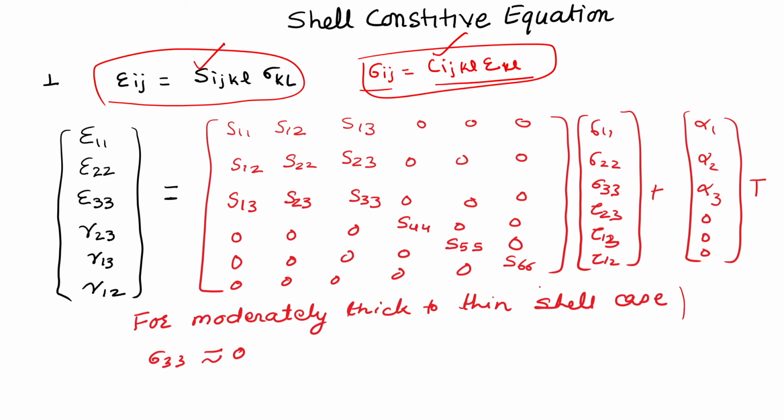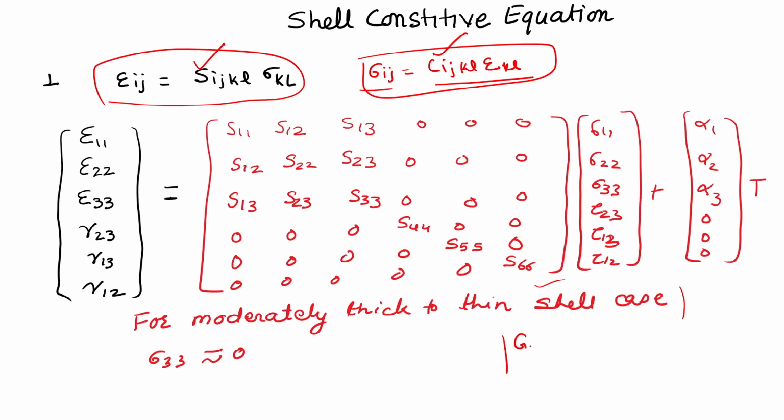Why have we chosen an orthotropic material? The topic of our shell is that the shell is made of a composite, or a composite shell or a sandwich shell. Generally, a graphite epoxy shell, a glass epoxy shell or any other kind of composite material is orthotropic. So, the material properties are orthotropic in nature, and we have chosen an orthotropic matrix. If we chose an isotropic matrix, some of the elements would be a function of the first, so S11, S22, S33 would be the same for an isotropic material.